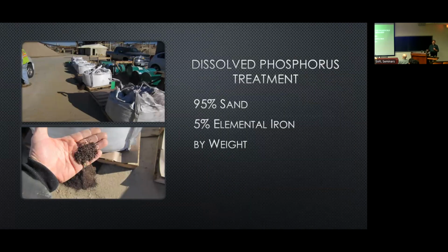So we started addressing this through two different approaches. One, we've got a lot of soluble phosphorus that's naturally occurring on the landscape. And about that same time, St. Anthony Falls Laboratory had developed the iron enhanced sand filter technology. And as Erin had pointed out, Barr had taken the lead in installing the first practice, and we were seeing positive results from that.